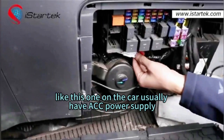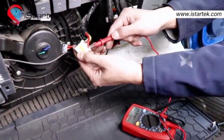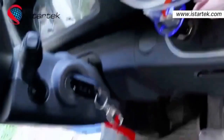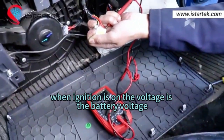White plugs like this one on the car usually have ACC power supply. For example, this red wire. When ignition is off, the voltage is 0. When ignition is on, the voltage is the battery voltage.